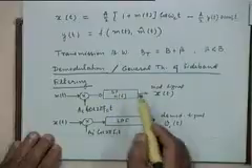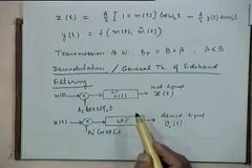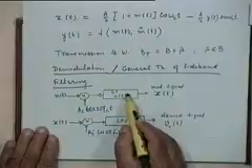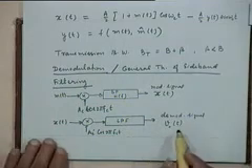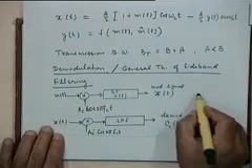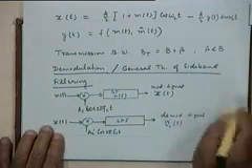So what kind of filter transfer function should this be? Suppose you want the upper sideband, so maybe this could be a high pass filter, but with some specific requirements. What should be the nature of H(f), so that is a question. Let me put it on the next page.